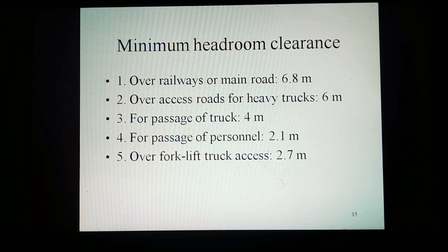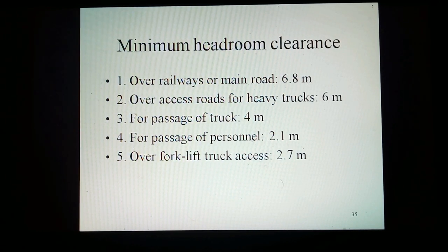Minimum headroom clearance for access ways shall be as follows. Over railways or main road, 6.8 meters. Over access road for heavy trucks, 6 meters. For passage of truck, 4 meters. For passage of personnel, 2.1 meters. Over forklift truck access, 2.7 meters.